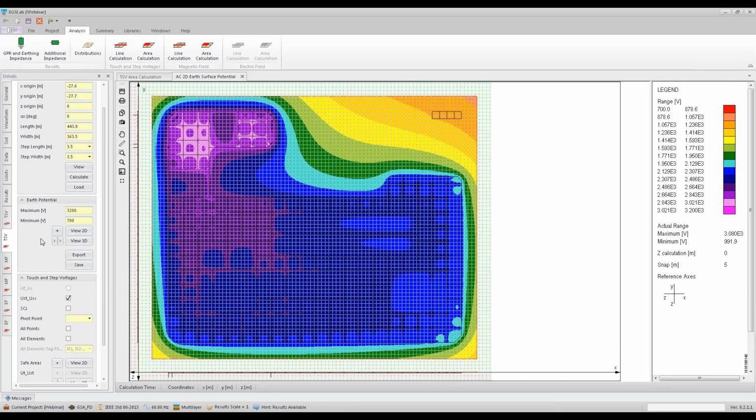In this case, it is very clear that we have high values, as you can read on the mouse that is hovering over the image. The high values are in the substation, here where the current is injected, and then there is a sort of bottleneck along these two wires that connect, let's say in a poor way, the substation to the remaining part of the earthing system. And so the remaining part of the earthing system has got another level, let's say, almost equipotential, not exactly equipotential, but let's say another level.